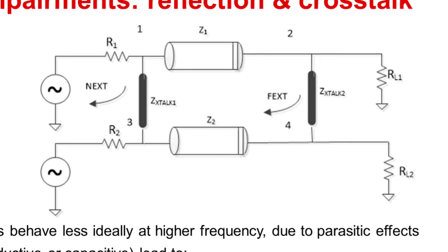Here we have 2 adjacent AC electrical sources, each launching a signal into the transmission line and subsequently onto an output termination. For either signal, reflections will occur to the extent that the transmission line impedance and output load resistance do not match. Poor transmission channel design, or the presence of parasitics, can lead to such undesired impedance variation.